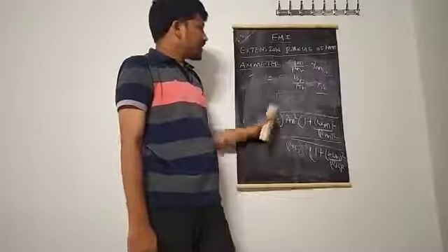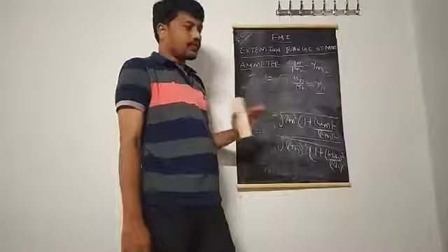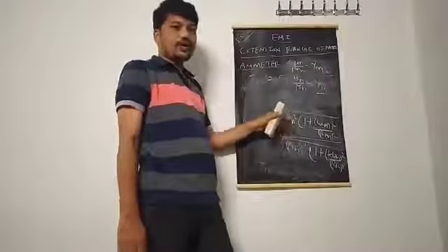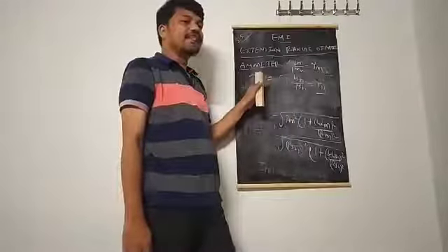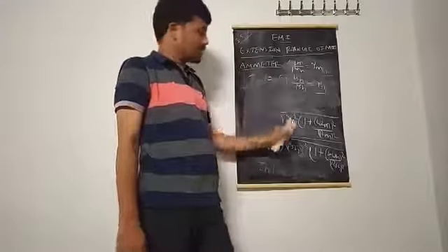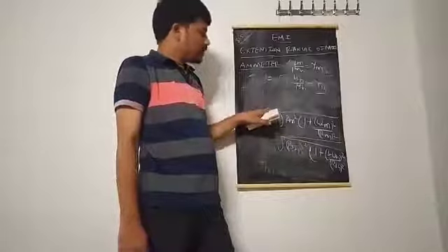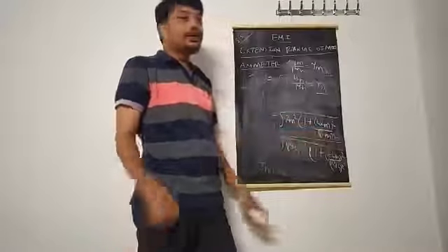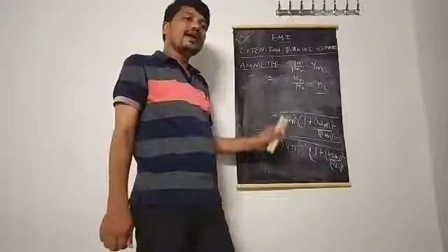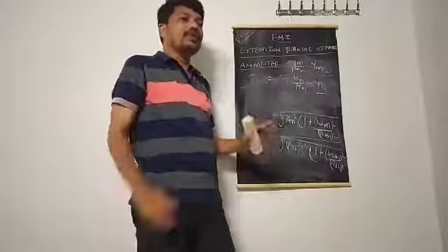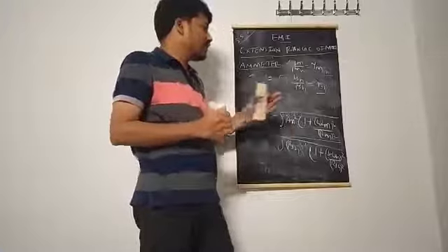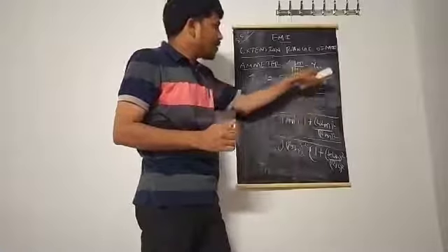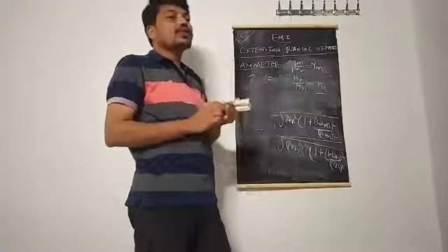So in the extension of the ammeter, this is fine up to here, but it depends upon the frequency. To make the moving iron ammeter independent of the frequency: up to here the ammeter is a function of frequency omega. To make the moving iron ammeter independent of frequency, what should you do? The meter time constant tau m should be equal to the shunt time constant.